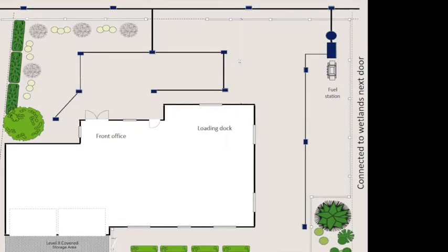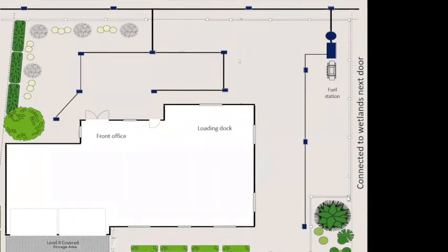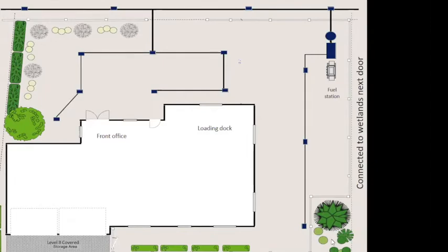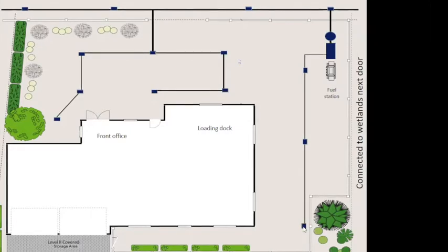What about the wetlands next door? One of the things when we developed this map, there's a direct connection here. This is the property line or a fence, but it can sometimes get underneath into the wetland with heavy storms. So putting in some kind of berm around this area so it's diverted and goes into the storm drain is what you want to think about.